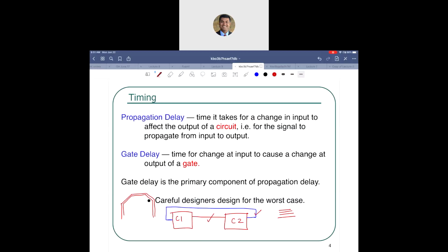Because at very, very high speeds, even a small difference in length matters a lot. So if you look at a very slow application, then you might not see those squiggly traces. But if you see a very high speed application, then you will see those squiggly traces, right? And computers, RAMs, and all the PCBs that you find in a computer, all those are high speed operation.